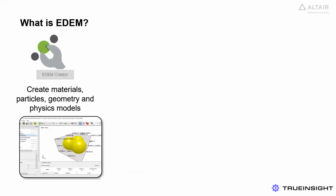So what is EDEM? The software itself is split into three main components: the creator, the simulator, and the analyst. The creator is where the parameters of the simulation are defined. This is done by defining the material and the equipment properties, particle to particle to geometry interactions, as well as geometry kinematics and physics models. Particle shapes are also defined here.